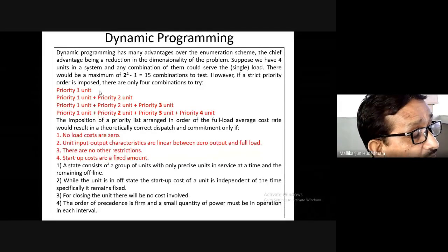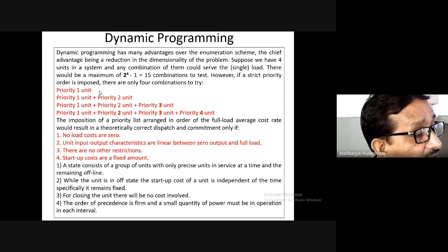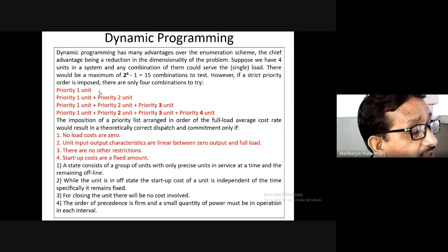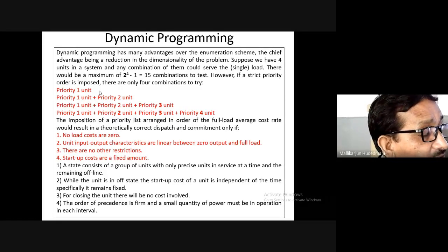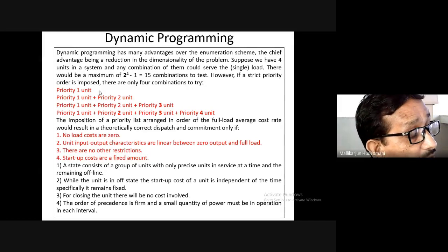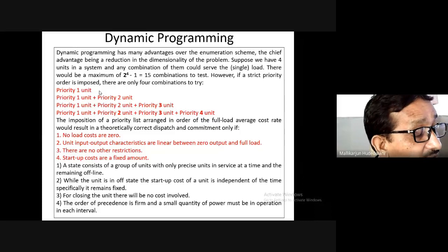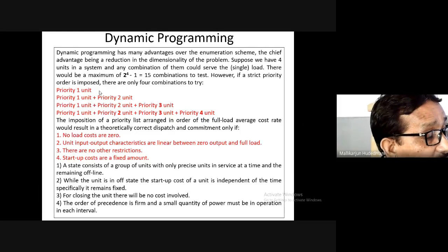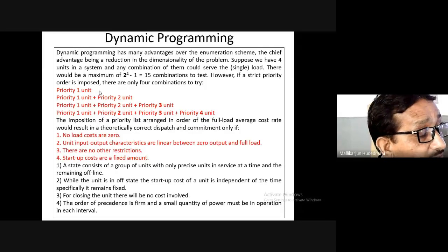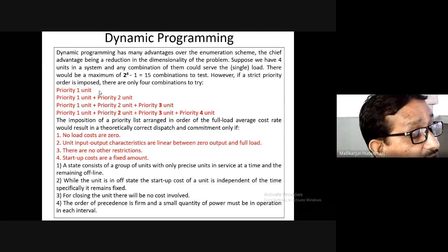The question is, you have picked a machine and it is generating for your requirement, and at a point it is unable to produce the megawatt required. You need a second generator to be combined. When you combine, you should see to it that from the remaining set of generators, you combine the one with the previous, so that those 2 can meet your requirement continuously further.